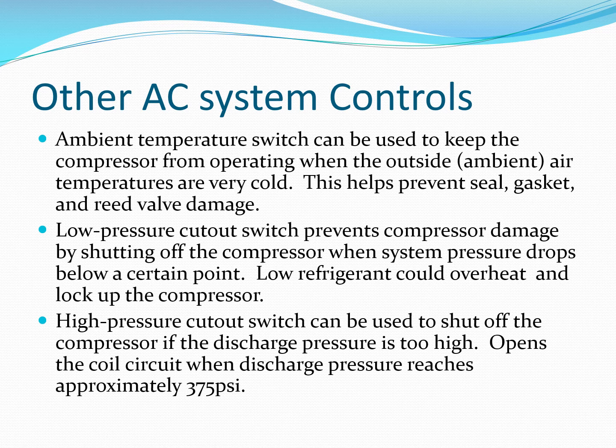Well, that's going to create hot air. There's no refrigerant problem at all, but because it seems that way to the uneducated, they just keep feeding refrigerant to the system, hoping to get it to start blowing cold. When in reality, what they're doing is they're overcharging the system, which is going to create high pressure, and even though the compressor wasn't the original problem, it could become an additional problem. And now the driver has two problems, and they don't even know it. So this is a very common issue, and this is why technicians really don't like that refrigerant is available to the uneducated person, because they actually do more damage than repair.